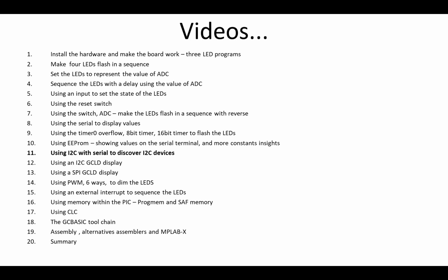Now, it's important to do discovery, otherwise, when you try to use a GLCD library or any, it doesn't matter what development tool you're using, you need to do discovery. And you need to do discovery from the microcontroller, not from a third-party device. A third-party device will tell you what's on the bus. It won't tell you that your chip, the master chip, is actually operating. Discovery will.